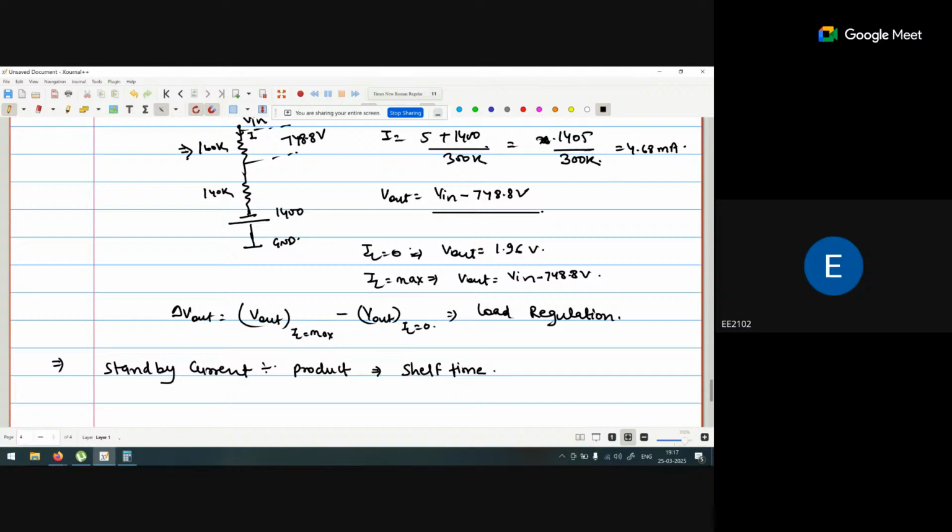And if in 2 months there is no voltage, we can say our rechargeable battery will be damaged. It will only work if you charge your battery regularly, or if there is some charge available for use. If your rechargeable battery is completely discharged today and you charge it after 10 days or 15 days, your rechargeable battery will not charge.